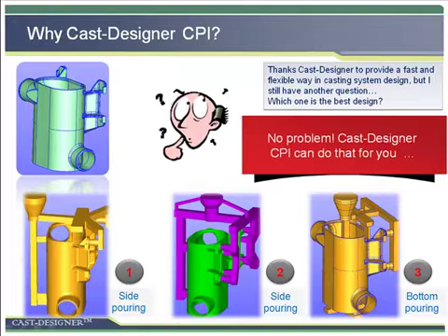Physical testing is one of the traditional methods, even if it wastes time and cost, and is also difficult for some cases. On the other hand, since 10 years ago, some companies began to use CAE tools to predict the problems and defects of the casting process. Of course, such a method is more advanced, however, it still cannot solve the headache of industry.